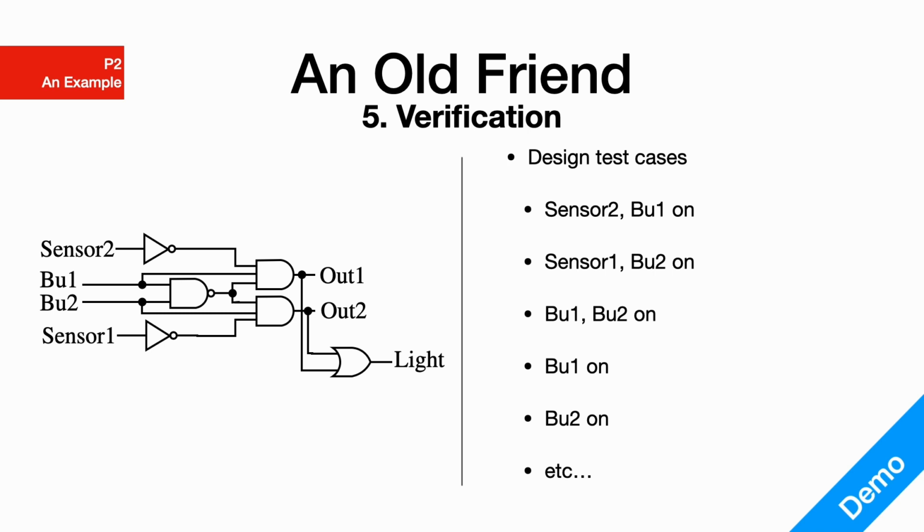Step 3, you would take the truth table or Boolean expression and perform optimization so that you're using the minimum amount of Boolean literals and binary operators so that it's easier to implement, essentially. Optimization, simplification of your Boolean expressions.